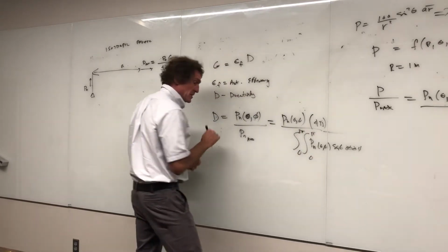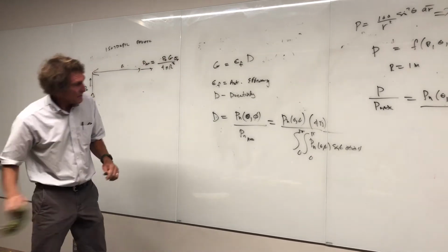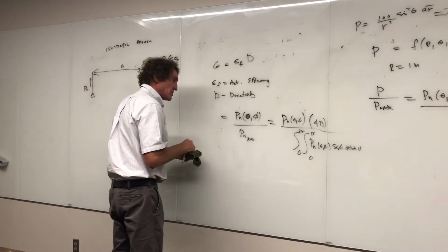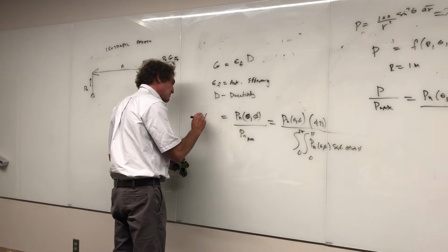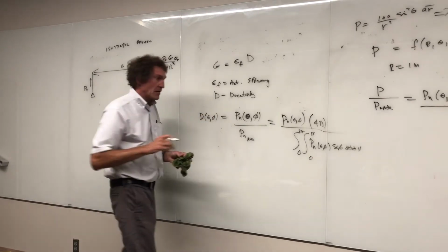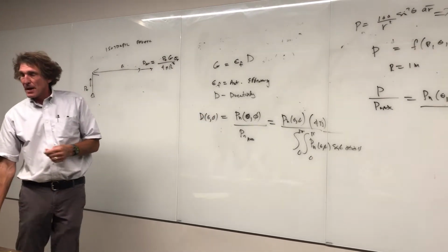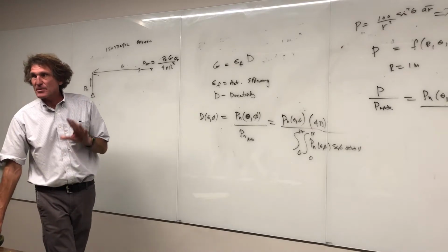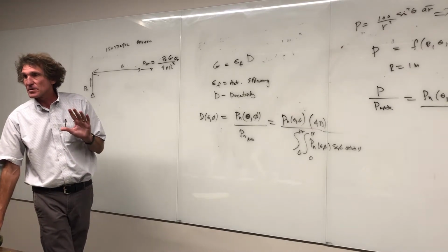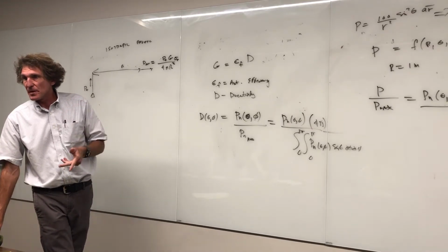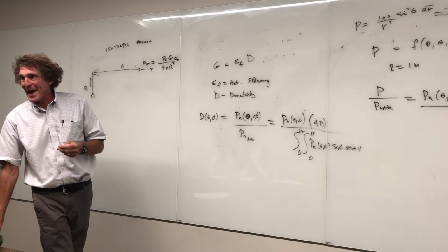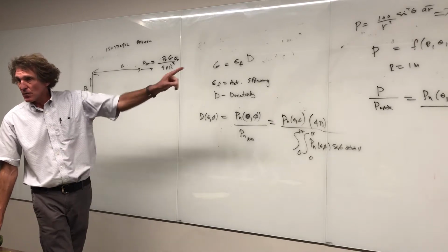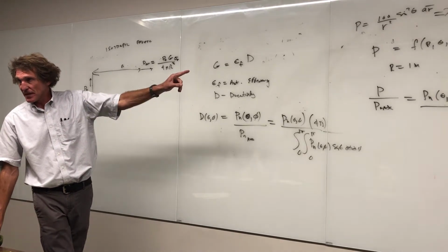And that's the equation. And you'll notice for gain, or for directivity right here, what you're actually getting is that directivity is a function of theta and phi, right? Now, I'm trying to do this in a way that's, at least to me, the most logical, to try to explain these concepts. This is getting more and more into the mathematical definition of how you calculate gain, if you knew what the average power density is. And that's where we're going next.